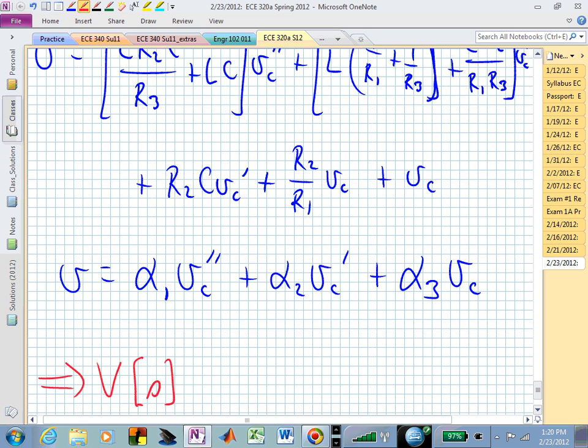And on the homework, they may say, oh, you have a DC source. If that's a DC source, then you'll want to replace that with maybe an amplitude, a magnitude of that DC divided by S, because that's like a unit step, a DC source. If they do not specify what the source is, you have to leave it in this unspecified form, capital V of S. Does that make sense?